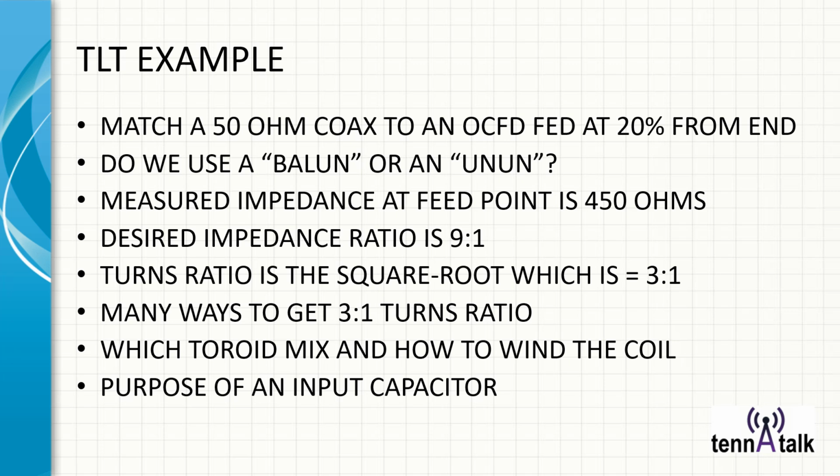You'll see that if you bring in a reactance on SimSmith, bring in a pure TLT, you'll have some positive reactance, which means slightly inductive. And a capacitor will be used to balance that in parallel. So you typically will see people putting a capacitor, typically 100 picofarad, across the input to a TLT to bring that closer to 50 ohms.